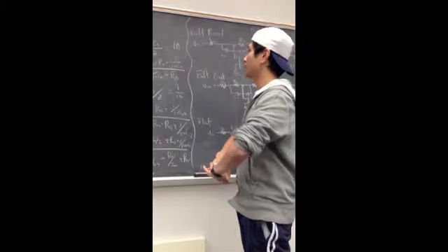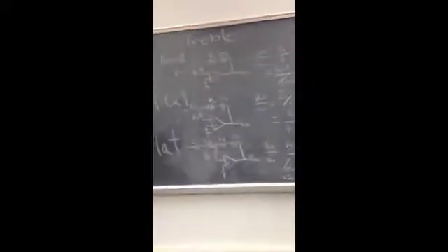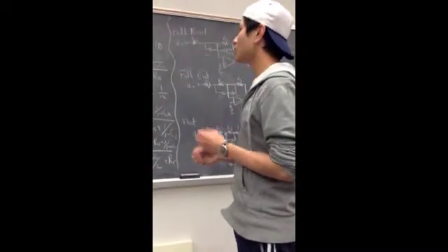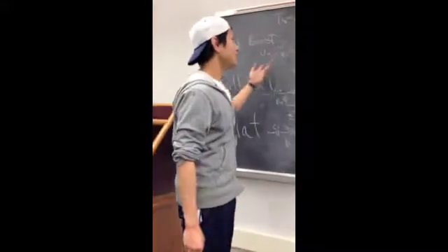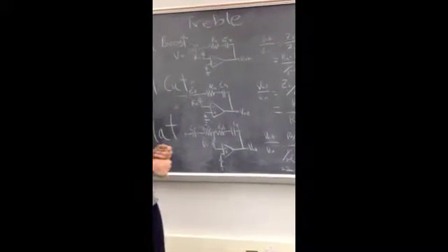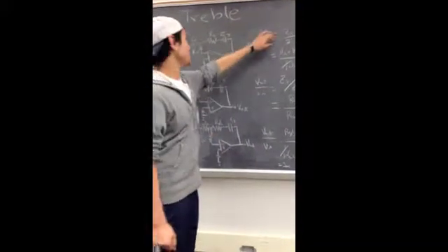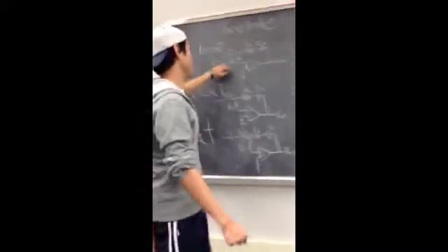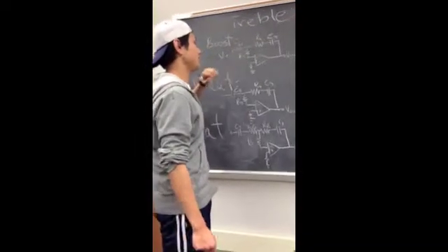The next step was how we were able to pick the capacitor and resistor values so that we can satisfy the requirements of 10 boost and 10 cut. We started off needing to figure out, as a result of an inverting amp, the ratio of gains. As we know from studying inverting amplifiers, that is the impedance that connects the output and the inverting input to the impedance that connects the input and the inverting input of the op amp.